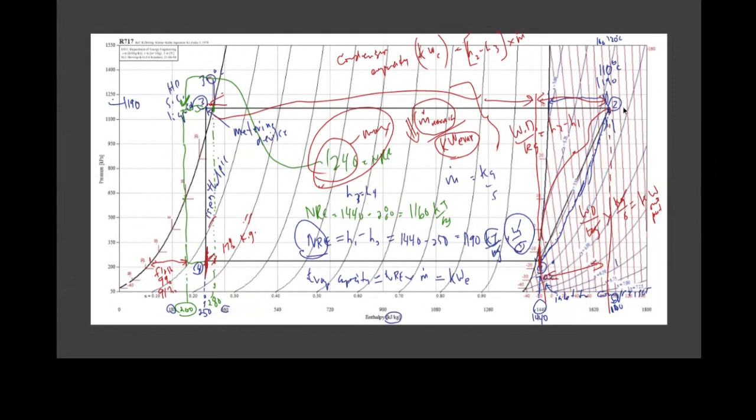time for a break. That's basically the recap of the theory. You know all of the bits of the equipment and what the system flow is. We go from point 1 to 2 to 3 to 4 to 1. We compress, we condense, we expand to low pressure, we boil, and we do this simultaneously. All of these functions are taking place simultaneously in a refrigeration plant.